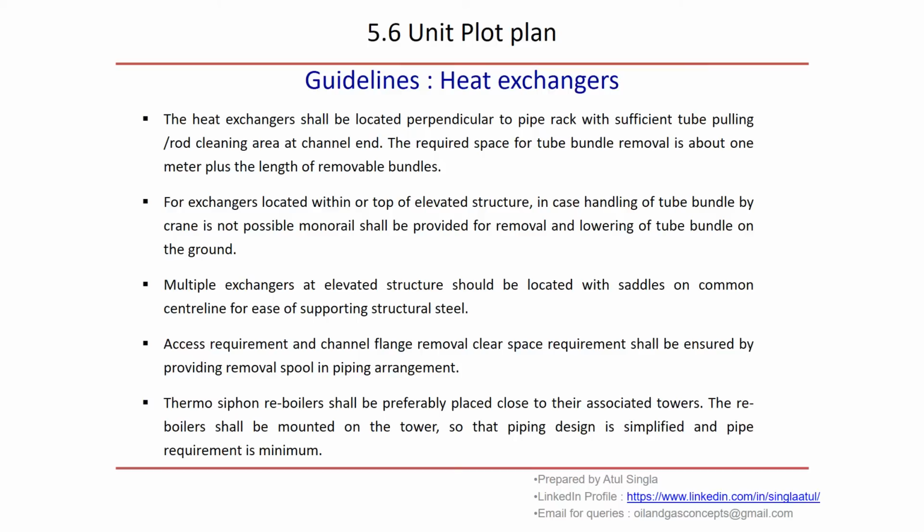Thermosiphon reboilers shall preferably be placed close to associated towers. Why do we have to locate these close to the tower? To have simplified and minimum piping requirements. These are connected. If the exchanger is connected to the column, then it should be mounted near the column only. So we will have an economical layout because of that.